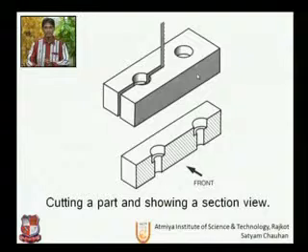So to clarify that view, we actually imagine that this piece is cut along the center axis of symmetry. So this is the axis of symmetry over here. If we are cutting this object imaginarily, it will be visible this way, and hence our front view will become a cutaway, and this will show a sectional view. Hence we don't need to draw a hidden line. It is clearly visible and easy to understand.